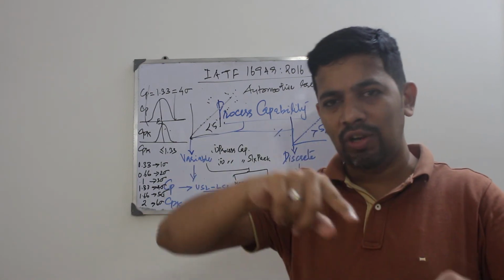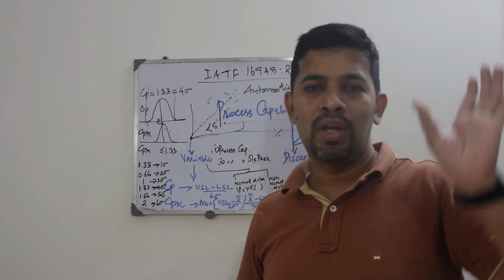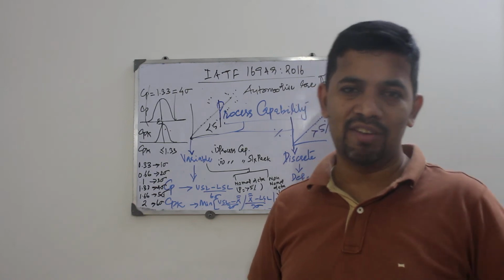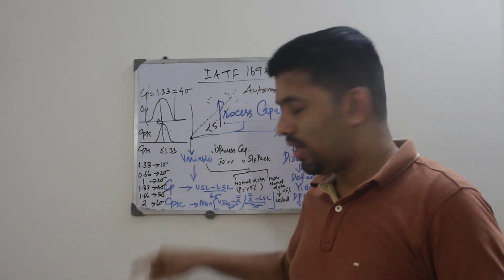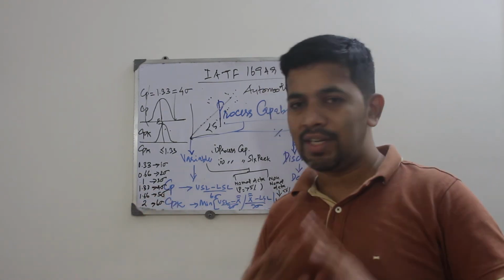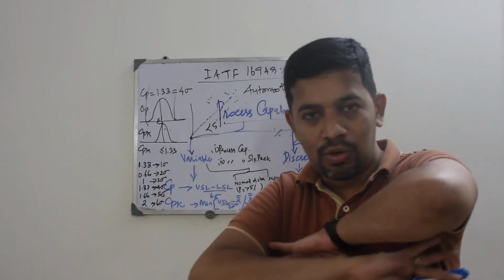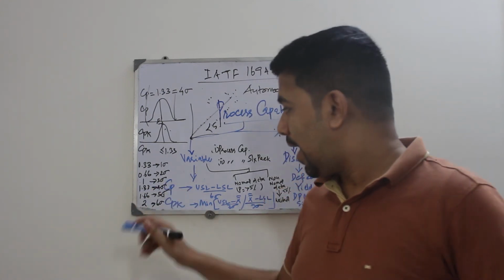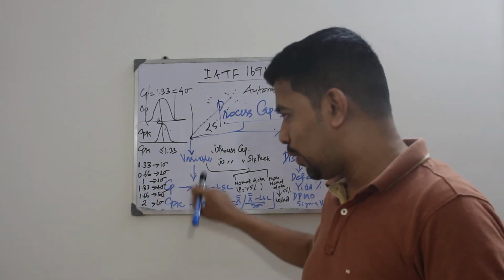It will give you a histogram, and on the left side you will have details like the N value, the LSL, USL, target, and the standard deviation within and overall. The right side gives values like 0.33 or 1.33. If it is 1.33, it means the 4 sigma process is capable. Anything less than 1, the process is not capable. Above 1.33 is capable, and more than that is good to have. That's what it denotes.